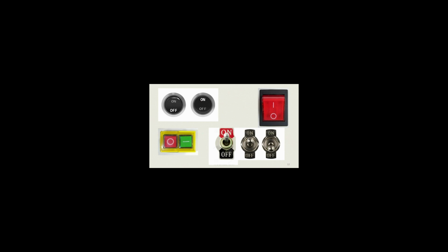So, a color coded is better, but once again its positioning is wrong. Traditionally it has been accepted that green is for start and you press anything red which is for emergency stop and for all stops. So, they should have been rotated. So, what looked like a very simple way of organizing things, suddenly we will discover it is not as simple as it looks.